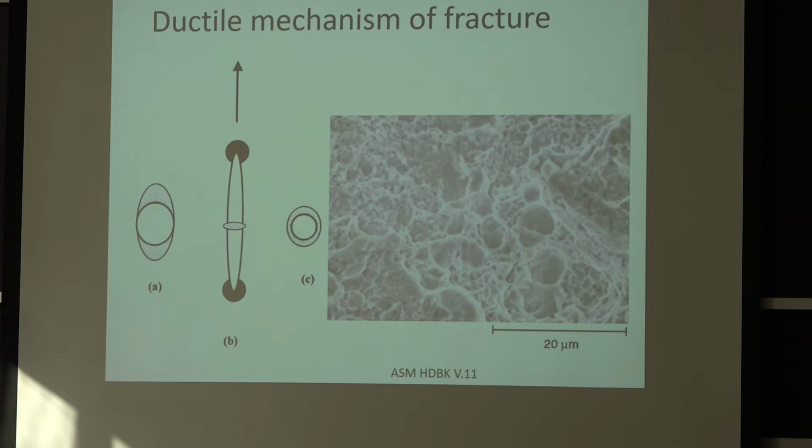You have too much of a height variation. The fracture surface is rough, so you can't see. So the use of the electron microscope in this case is not so much to go to much higher magnification as it is to have a bigger depth of field. So a range of distance to the fracture surface where you're still in focus.